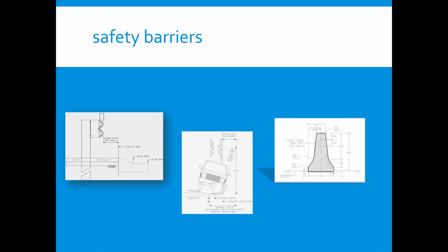Crash cushion systems are also used to protect hazards in confined locations, such as a junction of concrete barrier at a ramp nose. Concrete safety barriers are best suited to situations where there is little room between the barrier and the hazard. Typically, this occurs at narrow medians or in areas of restricted road cross-section. The greatest concern with concrete barriers is the method of termination.